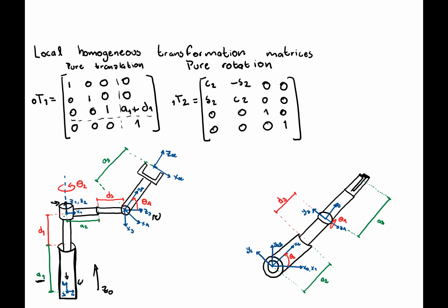Consider that y here is pointing towards the slide, not outside of the slide. So this is the y-axis of frame 2 pointing towards the slide. Now we're going to perform a rigid rotation around that one of 90 degrees. That is a positive direction because it's pointing towards the slide. So it's going to be a positive rotation of 90 degrees around the y-axis.